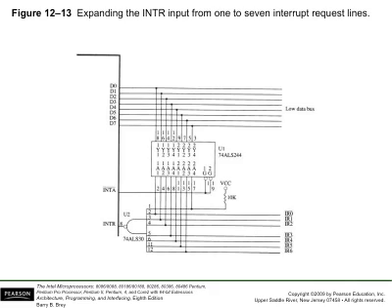So from this actual value, the microprocessor can tell which device or which combination of devices generated interrupts. And of course, in the corresponding interrupt service routine, you can deal with these different cases. If you have only one, then that's fine. If you have multiple devices generating interrupts altogether, then you can decide how to give them priorities.